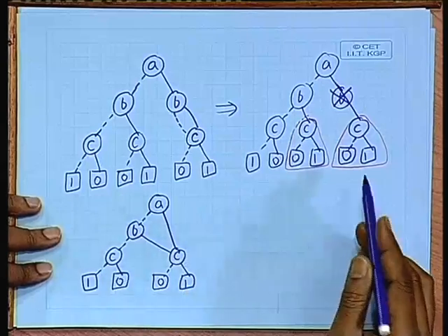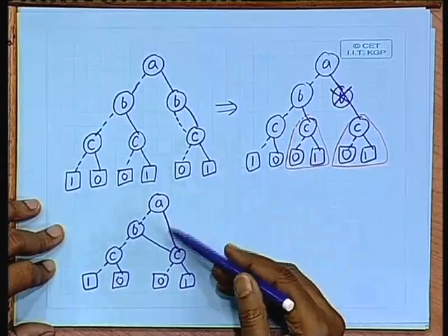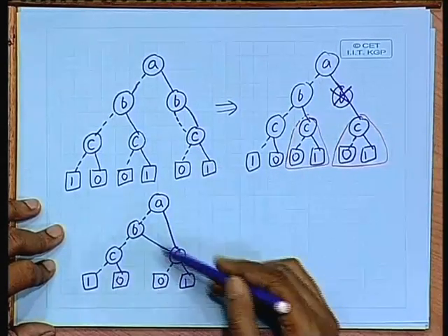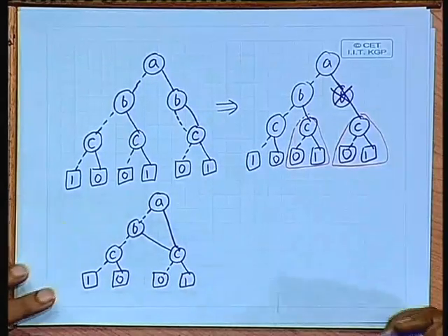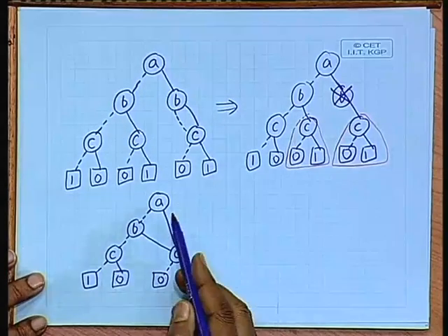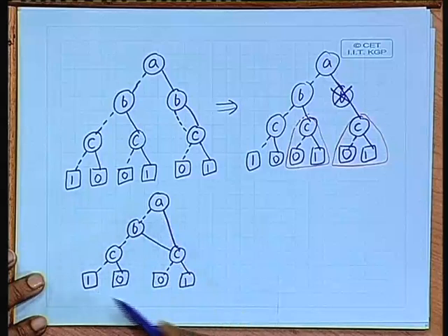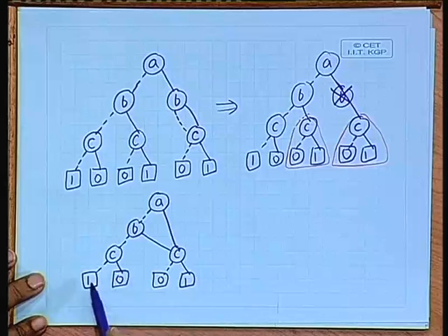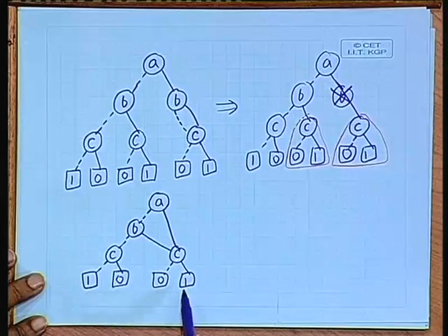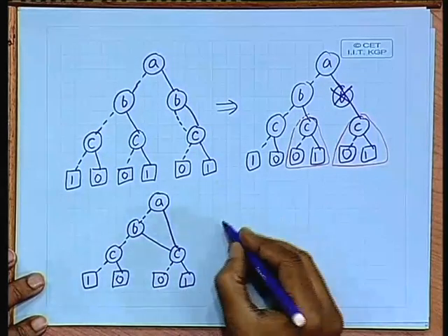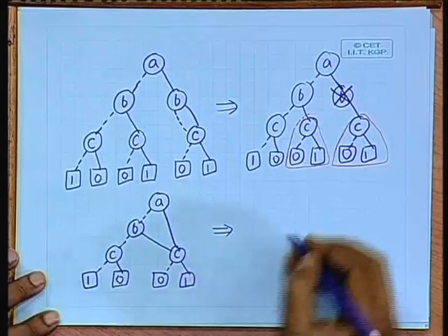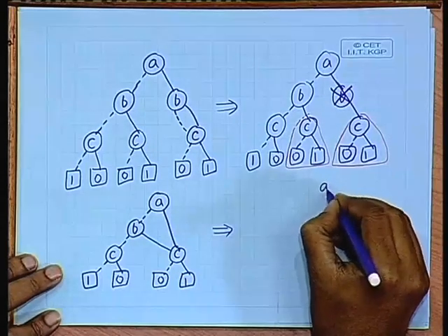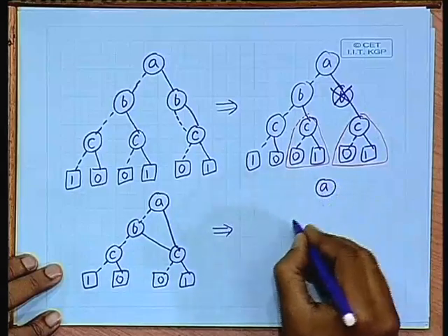So you see, as we carry out the transformation, the tree becomes a graph. It is no longer a tree now. Okay, this becomes a graph. So you inspect that if you can do any other transformation, you see that you cannot do anything else. As per those rules, only other than merging the zeros and ones, you cannot do anything else. So as the final step, you merge these zeros and ones into a single 0 node and a single 1 node.